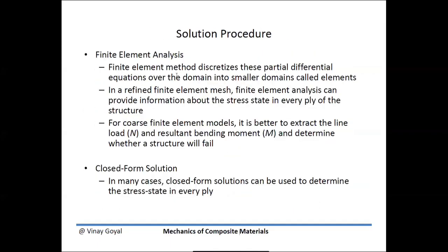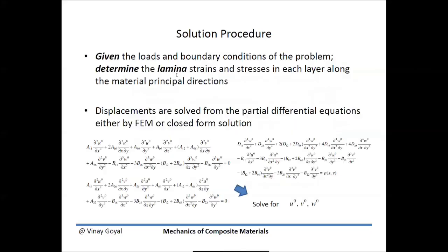And so if I were to have a finite element mesh, the finite element analysis provides you the ability of applying loads to a structure like an aircraft. And when you apply all these loads, it can then solve for these deflections U, V, and W that I talked about. And so it allows you to find those deflections in a way that's straightforward. Closed form solutions can also be performed, and I may cover a few later. But the bottom line is that a finite element analysis is the approach that you will use to solve these equations.